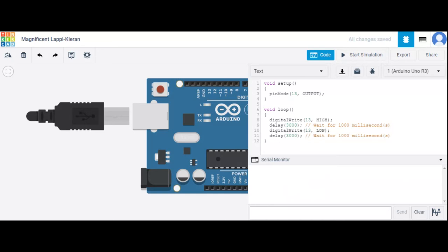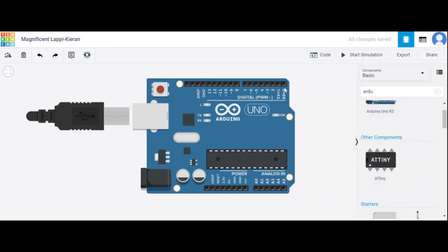Messages sent from Arduino to PC. So far we can send from PC to Arduino, but from Arduino to PC we can also send messages. How can you send these messages to the PC? They are sent from pin 1 and pin 0. Pin 1 is the transmitter, pin 0 is the receiver. They are directly connected to our laptop or our computer.